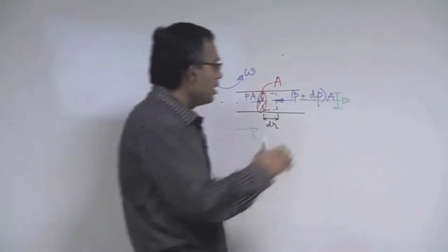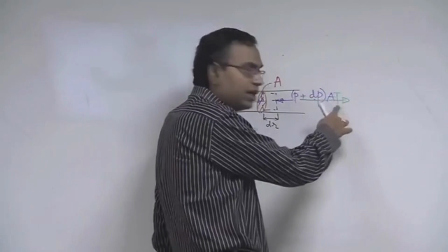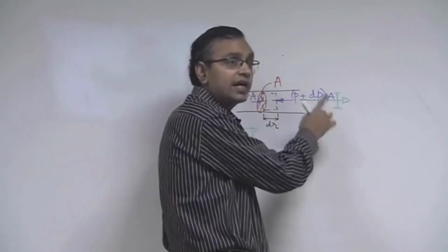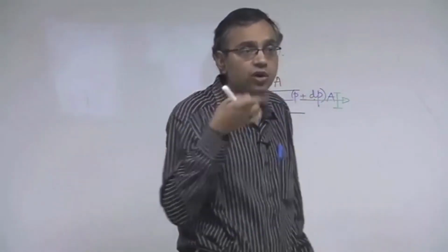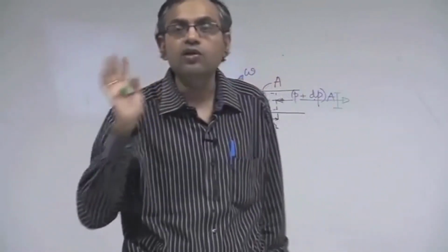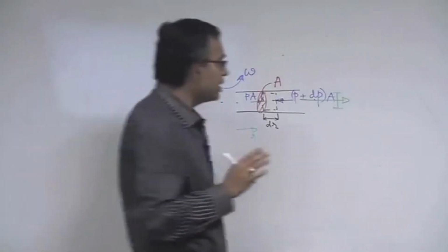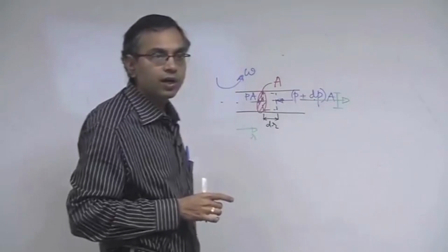Just to indicate that it is inertial force, I am drawing an arrow with I across it to mean that it is not actually an applied force, it is a pseudo force that is experienced because the observer is located on a non-inertial reference frame. So this is m omega square r.